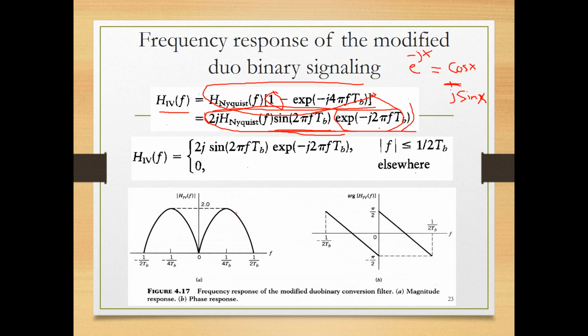Now, you got the functions, the formulas of the function in math. Can you draw them? You draw the amplitude of the frequency response. When you draw it, for example, at frequency equals 0, you substitute here f equals 0 and calculate the exponential of 0, e to the power 0, what? 1. 1 minus 1, 0. Anything multiplied by 0 is 0, then it's right. At 0, I will get a response equal to 0. See? Then I don't have a DC component. If I don't have a DC component, the signal can go through a wireless channel. I can send it through wireless.